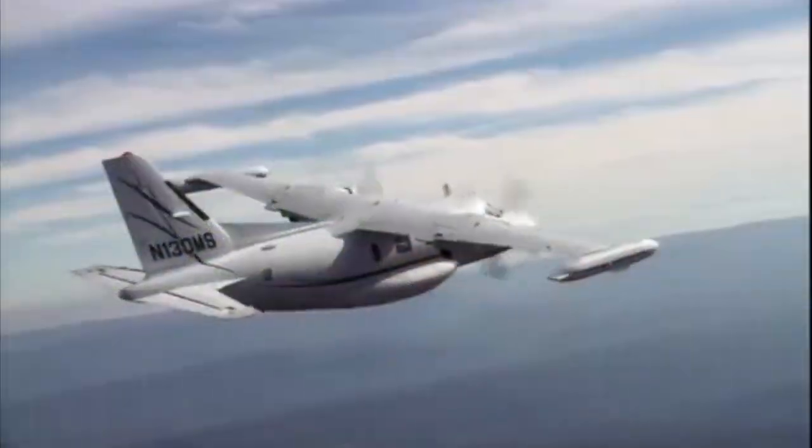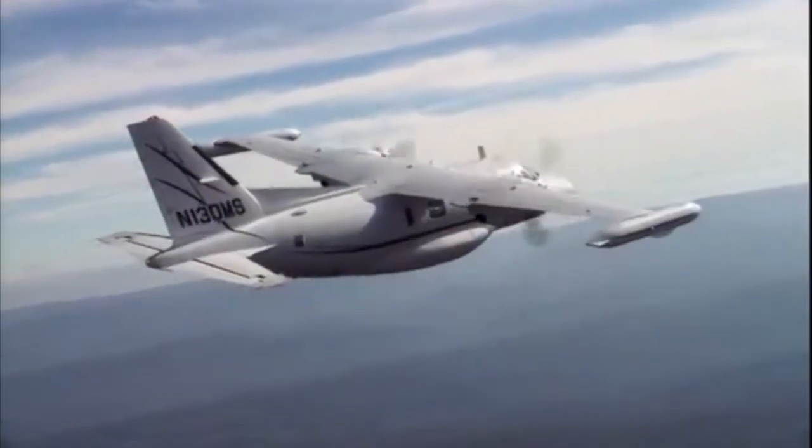And by electrical noise, what I mean is there's a lot of things that make pulses of electricity on the airplane. In specific, there are the beacons, which are mechanical rotating lights. Those are the red ones that you typically see on top and bottom of the airplane that flash. And on some airplanes those flash. In the MU2 they're mechanical and there's a little motor, and it's almost like the old style police light. It rotates back and forth, and so you've got that noise.